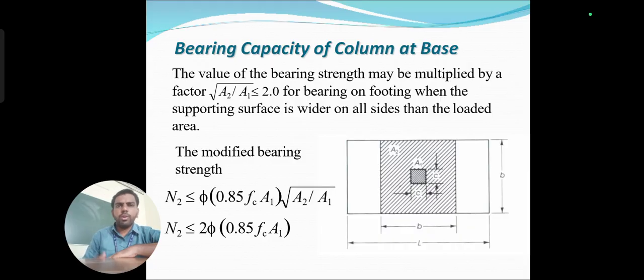All these loads should be transferred to the footings. The footing should be capable of providing high strength, stamina, and a high load bearing area. These are very important chapters to study from a real practical and realistic point of view, highly influenced by one-way shear, two-way shear, and bending moment. All these are very critical for finding the critical section of the footing.